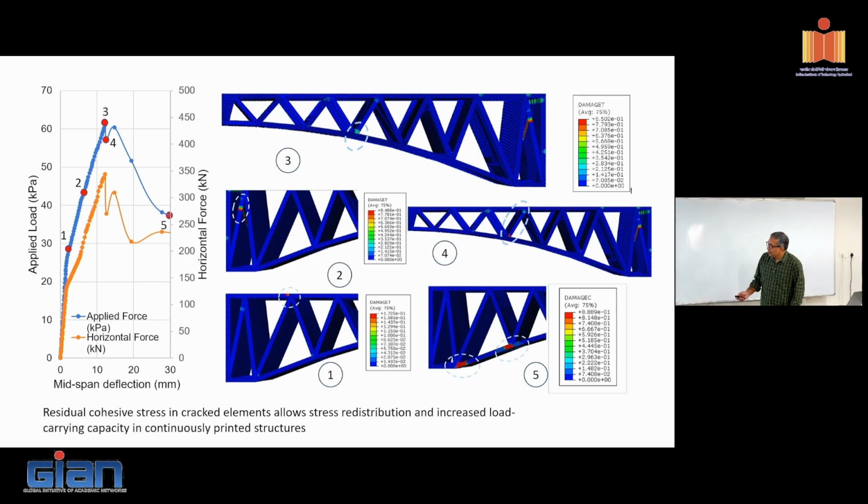And this is the tensile stress. So suppose I had a tension tie running across here. This is the tensile stress that would be required to support the bridge in place. So the required tension clearly builds up, as you're seeing. As I apply the load, the arch is kicking out, and the tensile force that would be required to hold it in place builds up. And then, of course, when the failure happens, the load drops and eventually it fails.